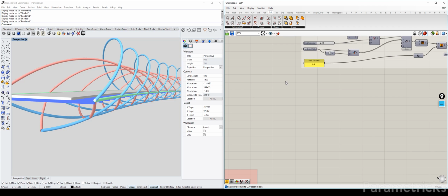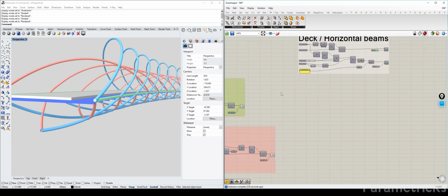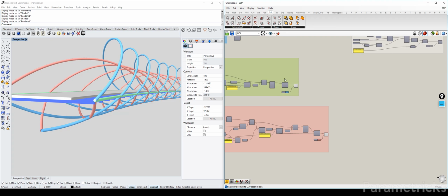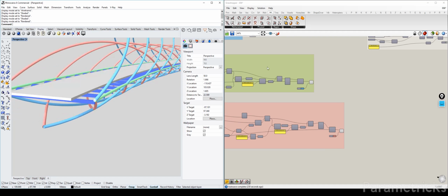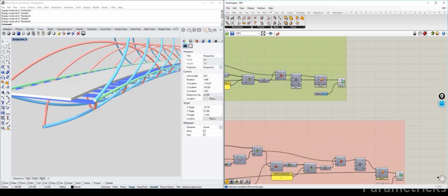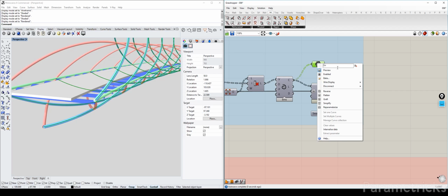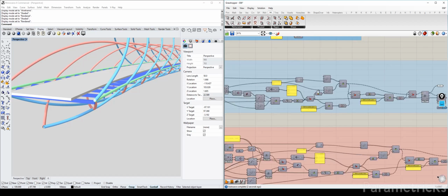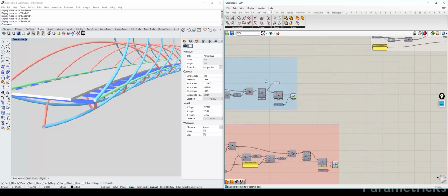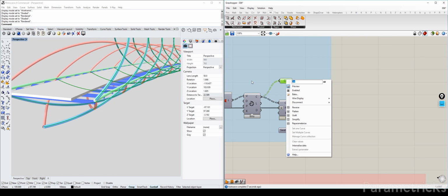Okay, let's see, what do we need? The first thing we need is obviously the 2 helix curves, because that's where the points intersect. So let's come here, and I found this is the big one. What we can do is create an output parameter for ourselves, and we just call this outer helix. So we could call this outer helix curves, something like that.